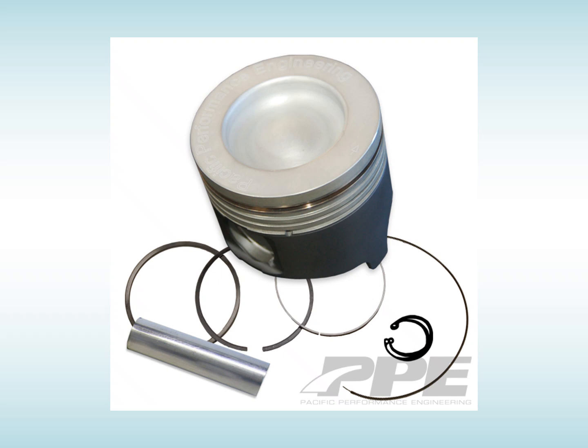Parts of a piston. You see obviously the piston there, the gudgeon pin or knuckle pin, as some people call it. You've got your three sets of rings. The top ring is generally a compression ring. The second ring is a second compression ring, and the bottom ring would be your oil scraper.